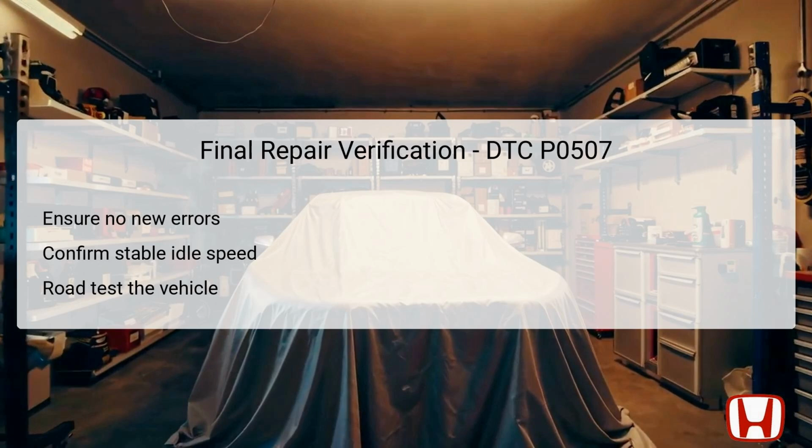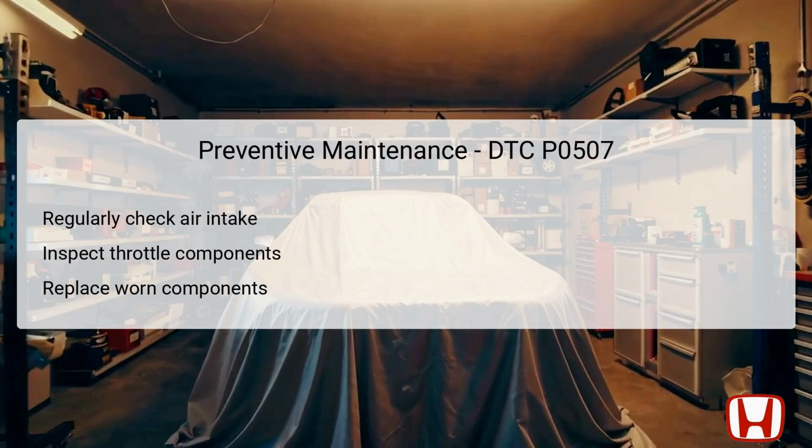Drive the vehicle under varying conditions to assess engine performance and observe if the idle remains stable across different scenarios, such as during stops at traffic lights or while transitioning between various speeds. Pay special attention to any erratic behavior or stalls which were symptomatic of the original problem. Successful road tests without occurrence of former symptoms indicate that the repair was effective and the system is now operating optimally.